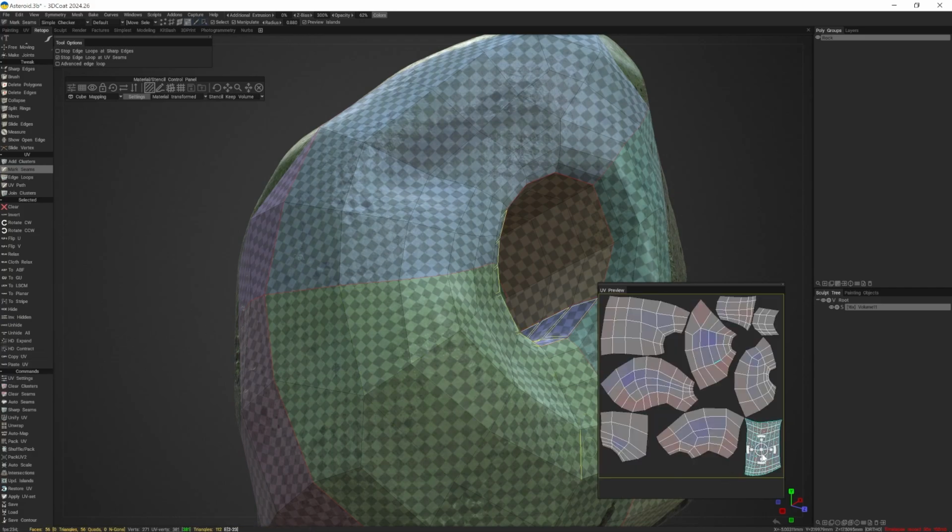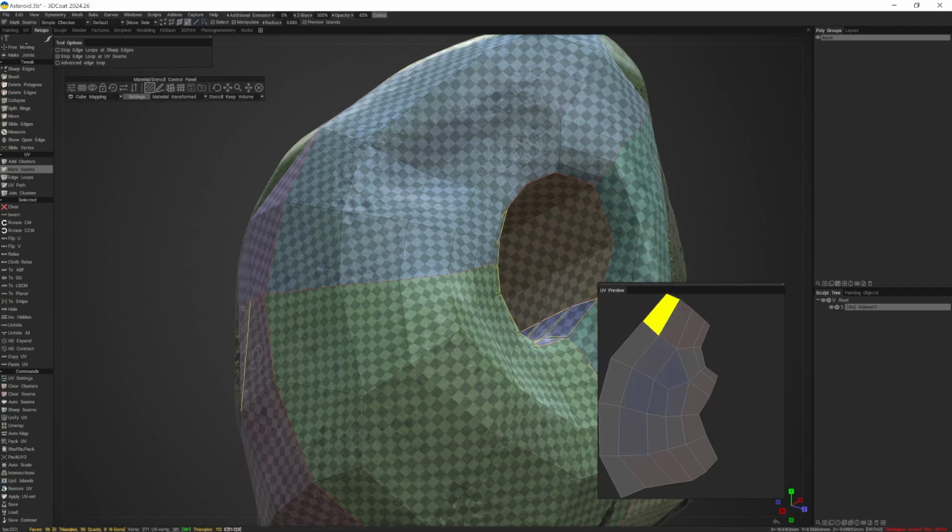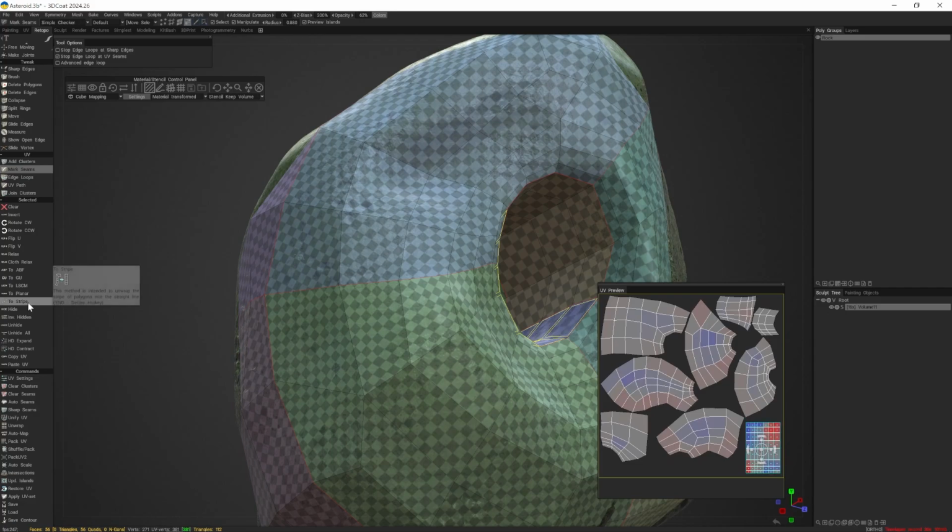There are some tools that we can use. If I select an island like this, on the selected island I can change the unwrap algorithm. So GU, I think, is the default here in 3D Coat, which is a proprietary algorithm that they use. It's global uniform. But there are others: ABF, angle-based flattening, LSCM, least squares conformal maps. To planar is more of a planar projection map. To strip, if I have something that's grid based, will square it out.